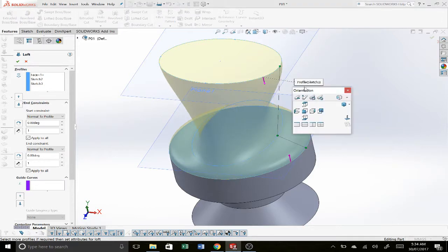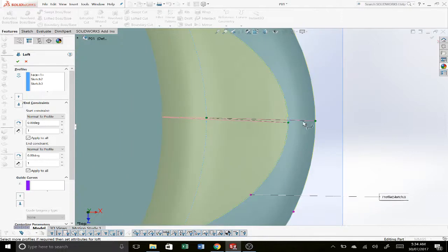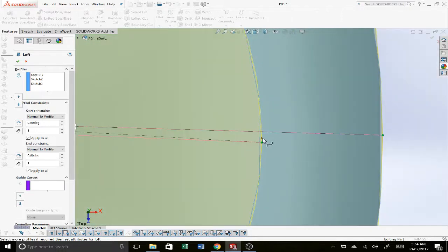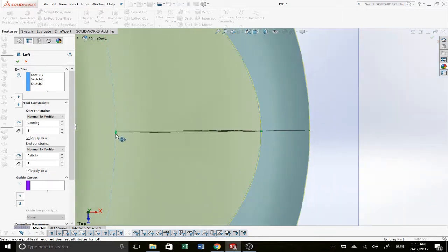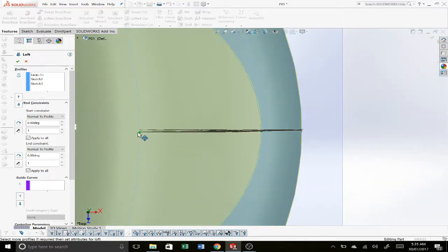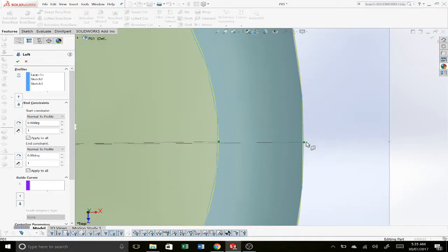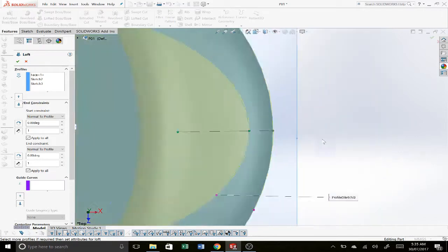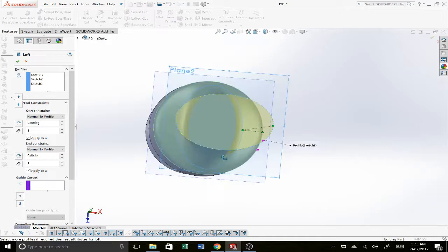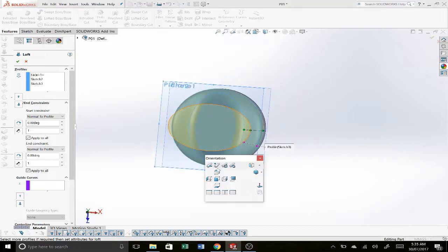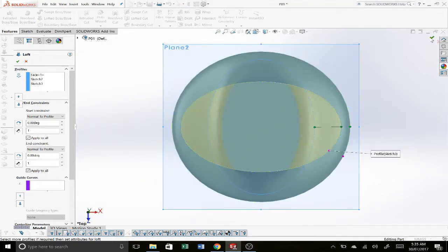So to just check how close they are, I'm going to come into my top view, and I'm going to try line it up with those endpoints, which we can see here, in my ellipse. So I'll drop that one there. I'll bring this one down to that endpoint, somewhere about there. And this is actually looking pretty good. It looks like I got a bit of room to tweak it. We'll just zoom in so we can really see what we're doing. Drop it about there. I think that's going to be about as good as we can get, so let's just leave it there. And now we can see we got rid of almost all of that twisting. It's looking a lot more symmetrical and even now, so that's quite excellent.